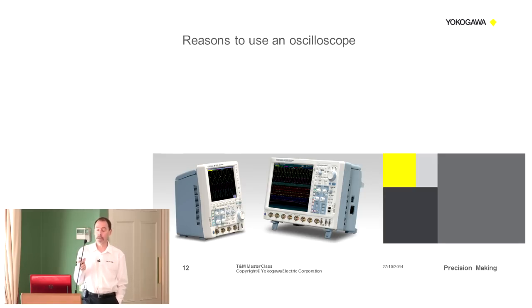But of course, modern devices and modern technologies and LED lighting or other high frequency usage mean that there are elements of higher frequencies, and that's why you've got power meters which are specified at 1 meg, for instance, or even 2 megs. There are issues with that to do with how you prove that your instrument is actually accurate at those frequencies, because there are no international standards which offer you a guarantee of calibration at 1 megahertz. Essentially 100 kilohertz is the maximum you can get.